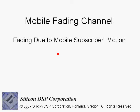In this section we will discuss mobile fading channels, and that is fading due to the motion of the station communicating with the access point or base station in the case of 802.16e. When a subscriber is in motion in a vehicle, the channel exhibits fading due to Doppler shift. As the vehicle approaches a base station, there is a Doppler shift and the frequency changes, and there is a spreading called the Doppler spread that results in fading in the time domain. That is, the envelope of the received carrier exhibits deep fades as a function of time.